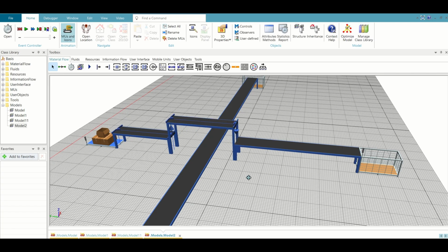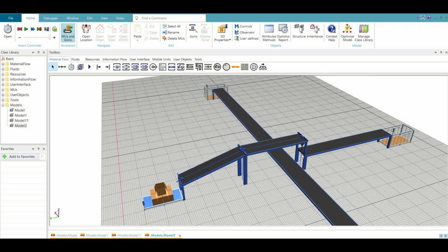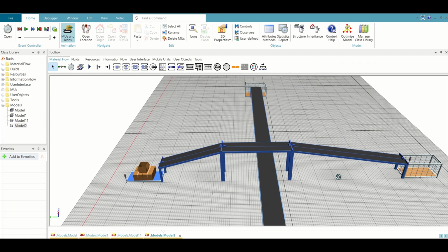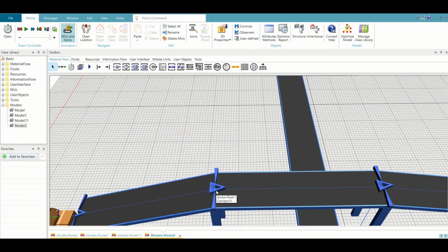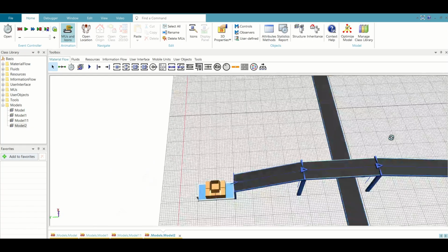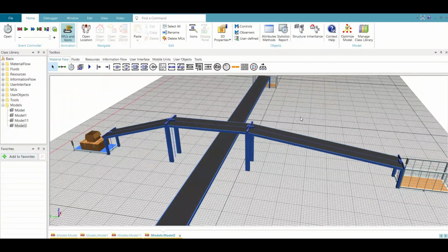Now what I'm gonna do is I'll make this anchor Control Shift upward, and then this Control Shift upward. I have this system connected going upward, but the problem here is that this is not gone. So similarly you can click on the manipulator here, also click on that anchor point and Control Shift up. Now, again, one point to mention here is that these anchor points which you see basically specify which direction the parts are going to go.